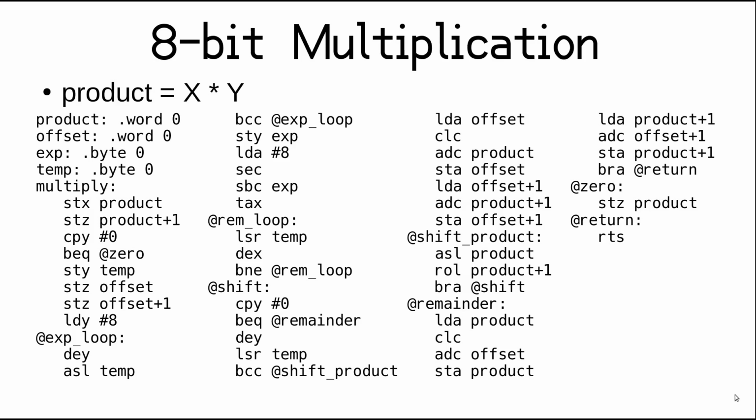This will give us the full 16-bit product of any 2 unsigned 8-bit values, but it takes up a fair amount of code and is not exactly super fast. So chances are you don't want to do exactly this in your own program, but maybe some sort of modified and optimized form that works for your specific use case. In our example program later, we'll see a full 16-bit version of this algorithm and go over it in greater detail.